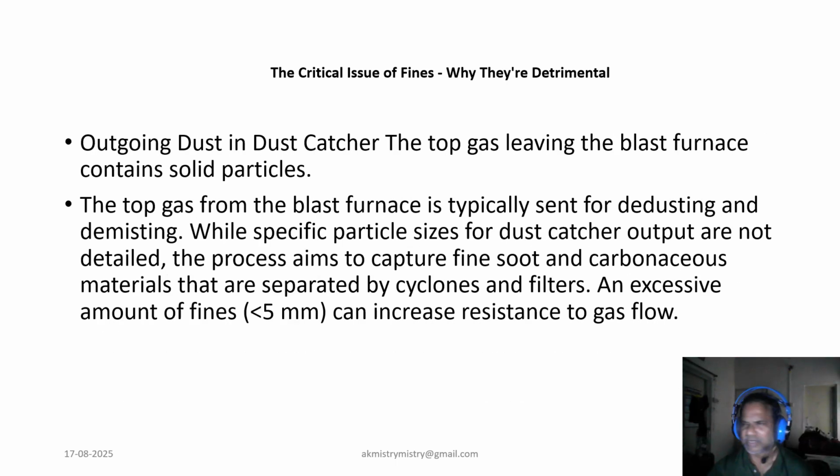So we are coming to this slide, which is about the fines repeatedly coming into the system. Gas flow resistance is greatly influenced by the ratio of small and large particles. This is because the smaller particles can fill the voids between the larger ones, drastically reducing permeability, as we all know fundamentally. Therefore, controlling fines, which are typically defined as less than 5 mm, is absolutely crucial.